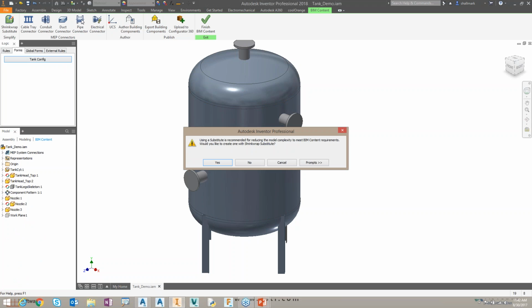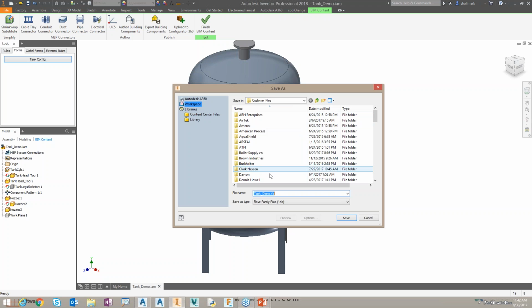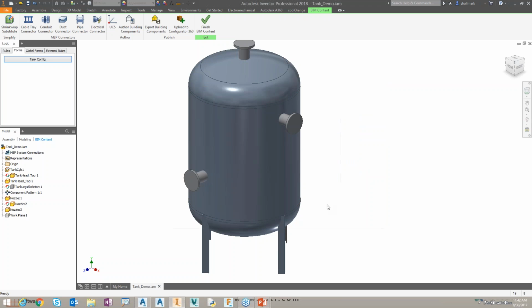We could put pipe connectors on here and go ahead and define these sizes and things, but I like to do that in Plant instead. So I typically leave that off, but what I can do is create an ADSK, put it wherever that project is located in Plant, say maybe in your related files folder or your equipment templates folder, somewhere where it can be found inside the project, and save it out to that ADSK.